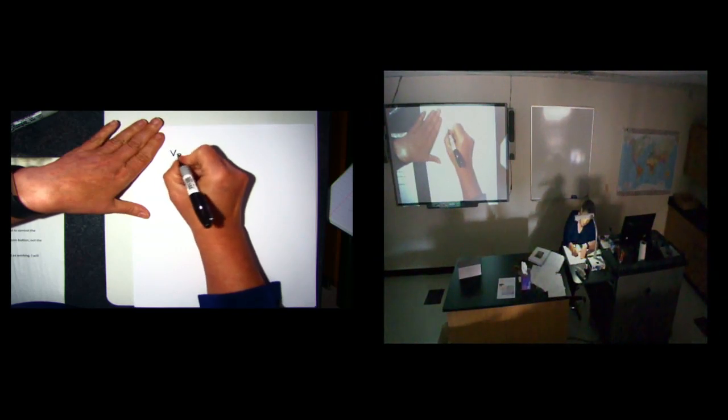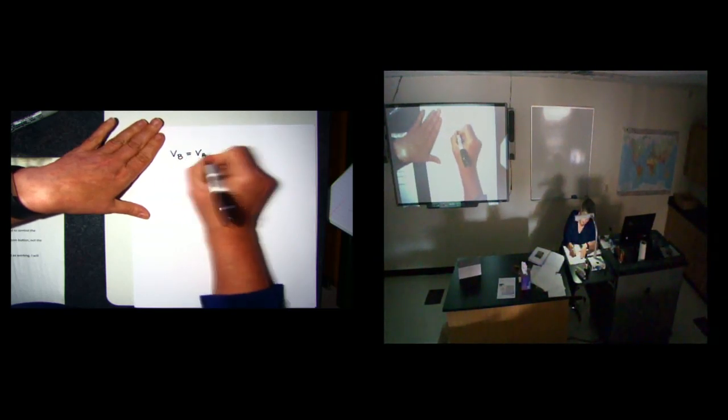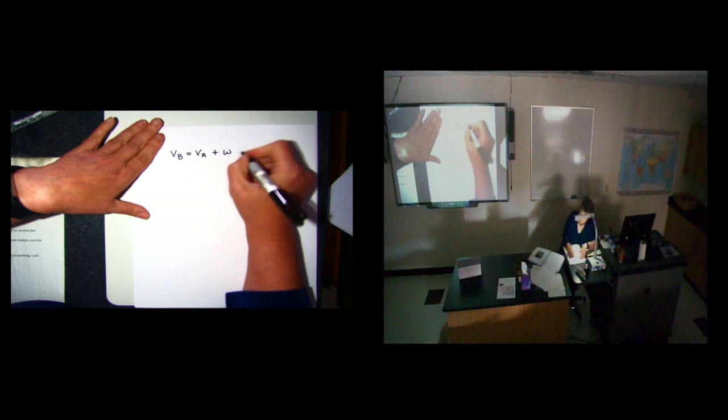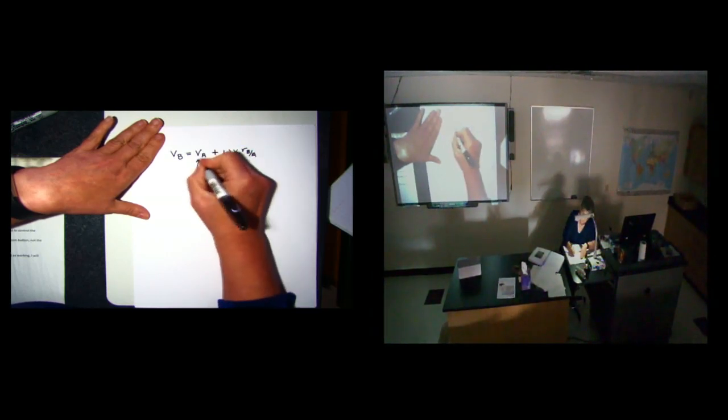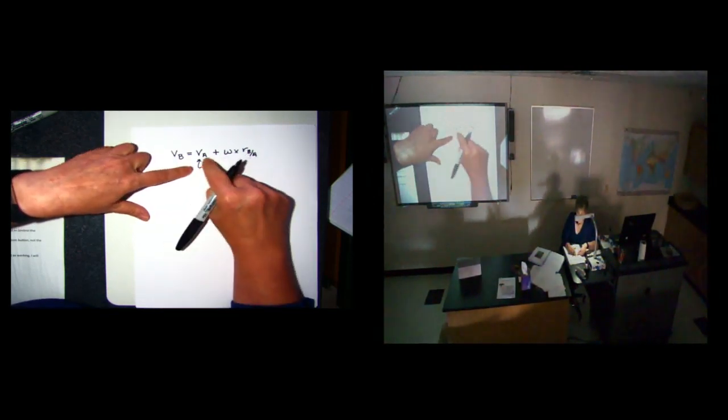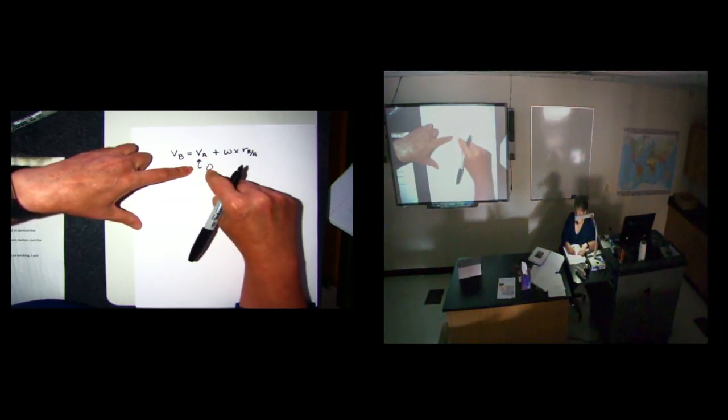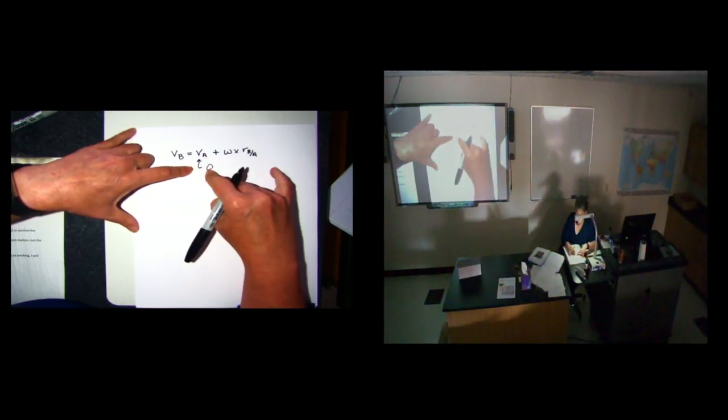This is going to give me my point of zero velocity. So if I'm working problems to figure out how other things are working, if I'm working from this point, I can simplify a great deal by being able to get that spot. The real trick comes to figuring out where that piece is.